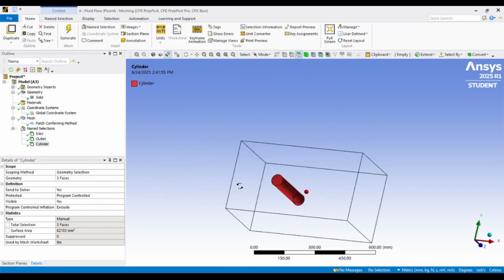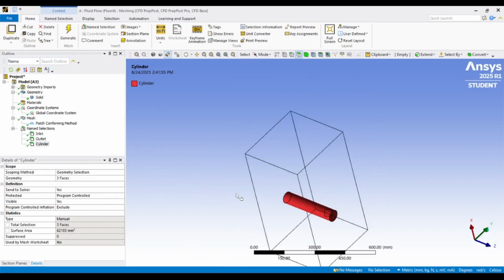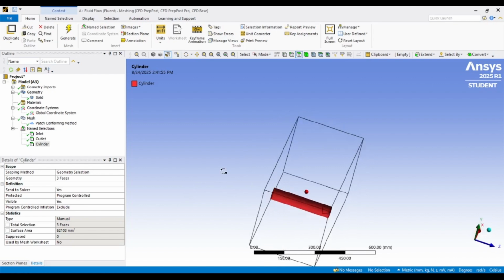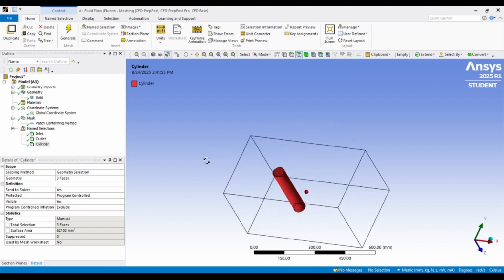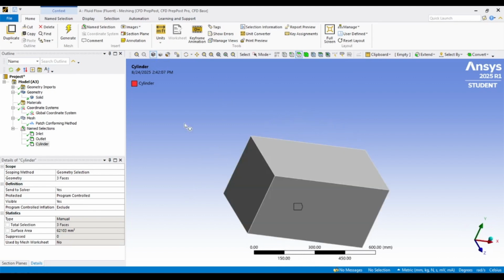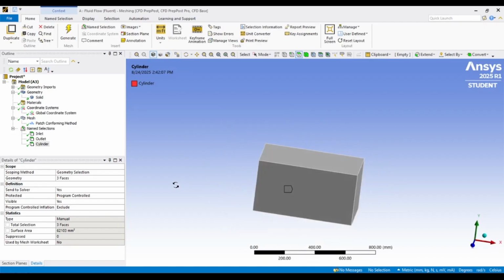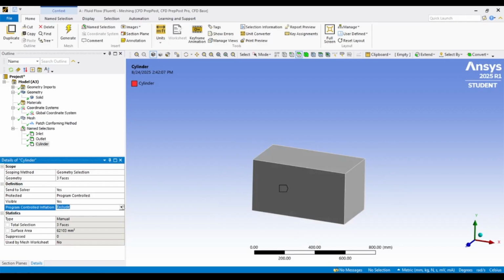In a transient vortex shedding regime, two distinct vortices, one rotating clockwise and the other counterclockwise, will appear alternately behind the cylinder, forming the characteristic von Karman vortex street. The spacing and intensity of these vortices depend on the Reynolds number and turbulence model used. For instance, as Reynolds number increases, vortices become more chaotic and the wake broadens.